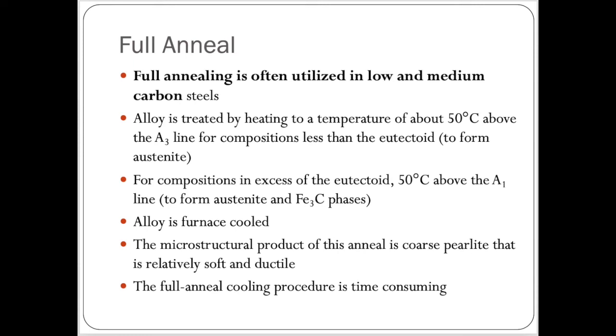The alloy in the furnace is cooled, that is, the heat treating furnace is turned off and both furnace and steel cool to room temperature at the same rate, which takes several hours. The microstructural product of this anneal is coarse pearlite, in addition to any proeutectoid phase, that is relatively soft and ductile. The full anneal cooling procedure is time consuming. However, a microstructure having small grains and a uniform grain structure results.